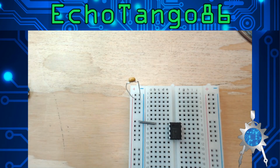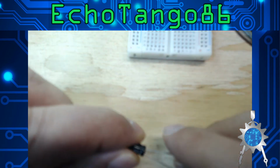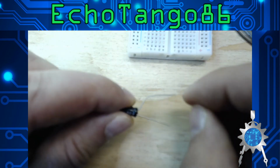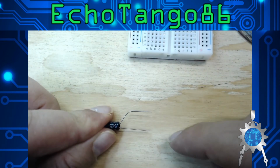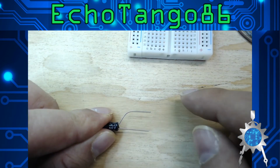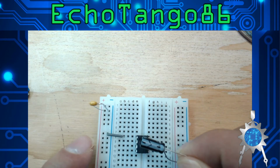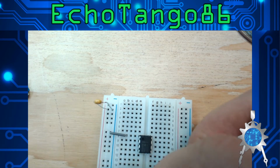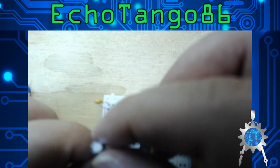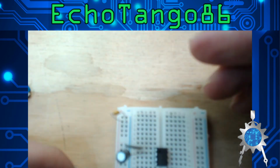Pin 2 is going to have our polar capacitor. Now what I like to do with that is I like to bend it, and kind of do that. It puts them in a little more of an even situation. Again, you're looking for this to go on the ground side, like how this wire is plugged in, the blue. So, grab it, put it in there, like that.